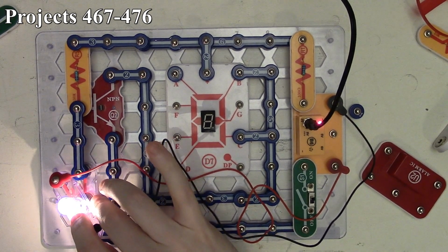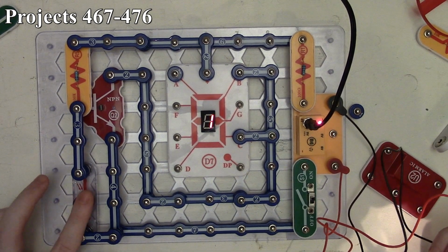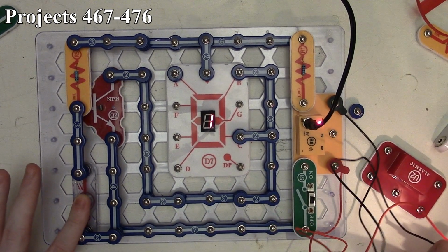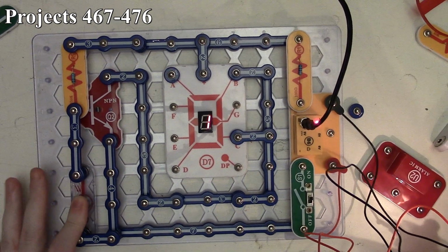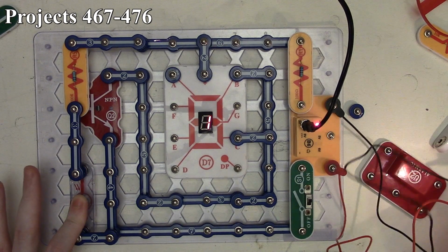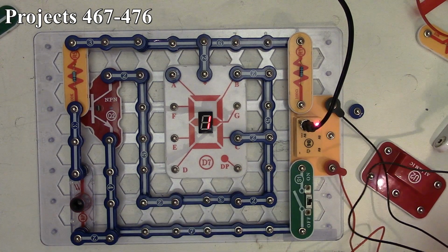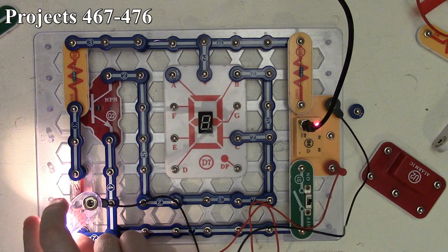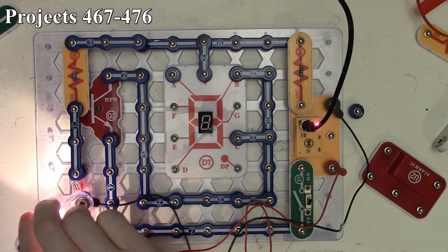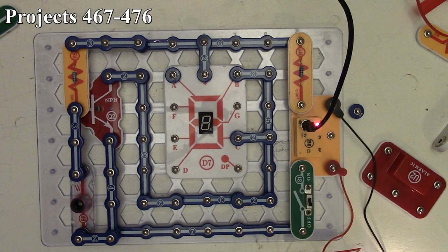Now, as I take our 6-volt lamp away from the photoresistor, the number 1 lights up, and if I cover the photoresistor entirely, well, it lights up nice and bright, because again now there's so much resistance on that photoresistor that the NPN transistor can pretty much fully turn on, and we get our number 1 showing on there. And again, as I let light into the photoresistor, it gets dimmer. You can bring the 6-volt lamp over to make it really bright. Well, now of course it goes completely out because we've lowered the resistance so much there. So that is how Project 467 works.